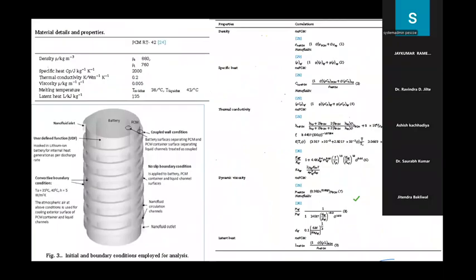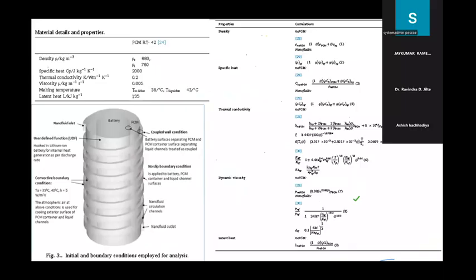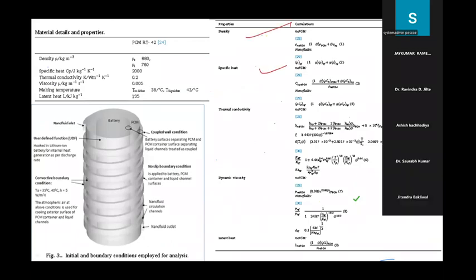We require the generation of the properties of the nanofluids. In the literature, many equations are available which can be utilized to calculate the density, specific heat, conductivity, and viscosity of the nanoparticles, and the latent heat of the phase change materials. You try to utilize different sources, use an Excel sheet to generate these properties, and then these properties will be fed into the modeling and the simulation.